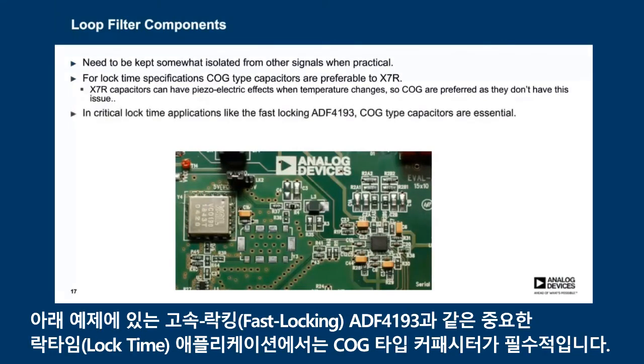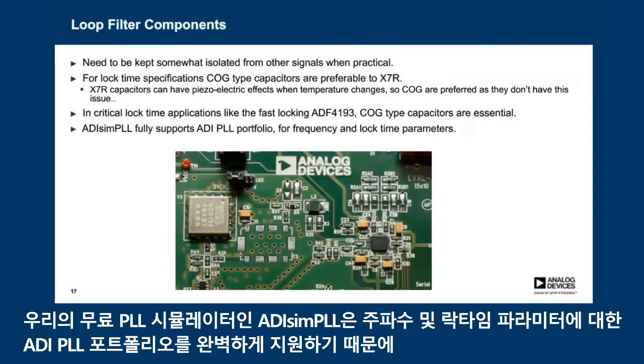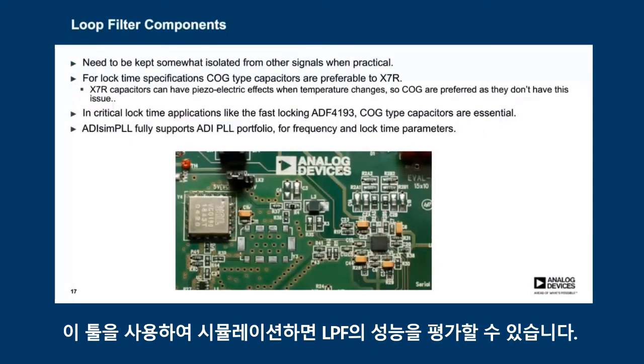And in critical lock time applications like the fast locking ADF4193, which is in the example below, COG type capacitors are essential. Worth noting that ADI Sim PLL, our free PLL simulator, fully supports the ADI PLL portfolio for frequency and lock time parameters, so you can get a good estimate of how the low pass filter will perform by simulating it